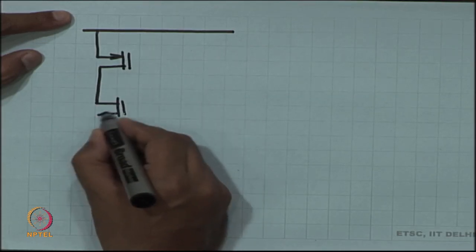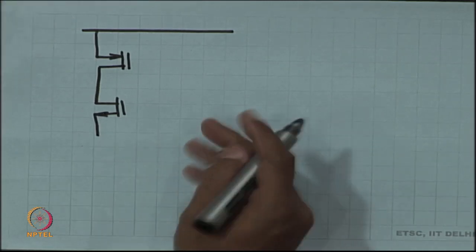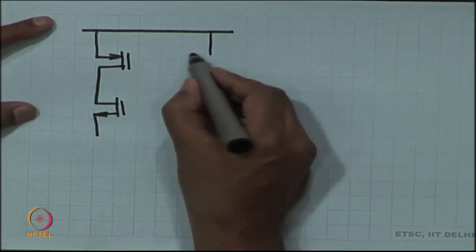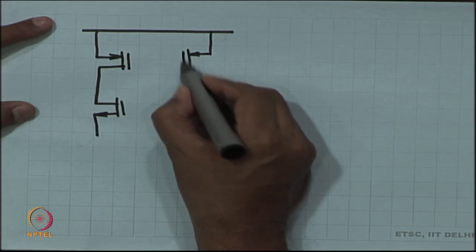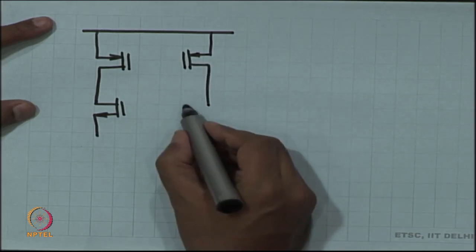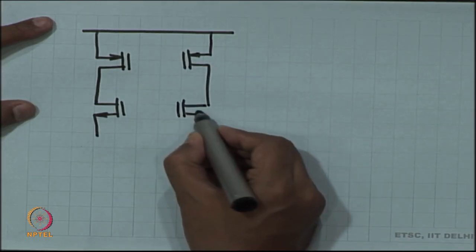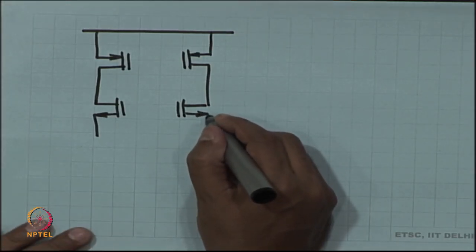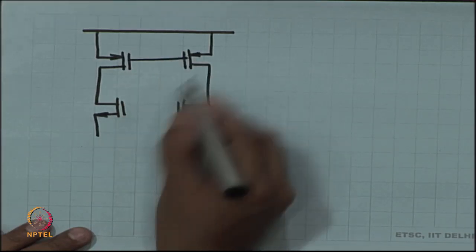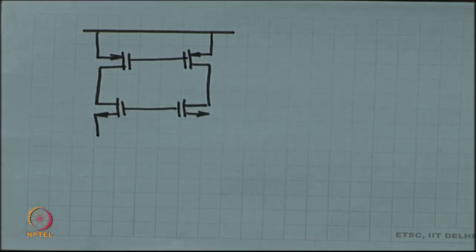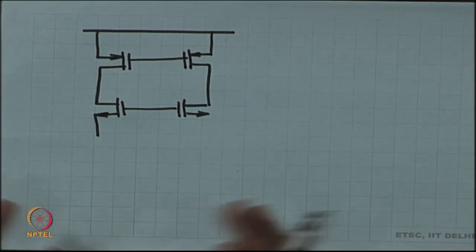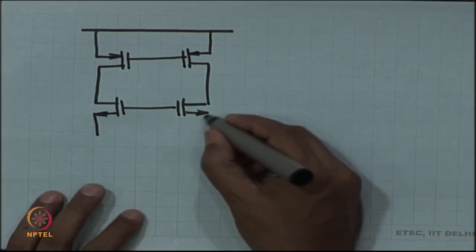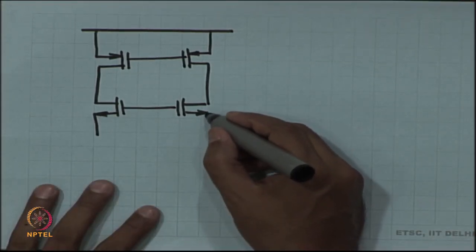And the way we were doing it, first we said let us just have one PMOS current mirror and an NMOS current mirror, but that did not quite work out because it could have conducted any amount of current. Next, we had a PMOS current mirror and we changed the ratio on that. The NMOS current mirror had a ratio of 1:1, in which case we found that no current goes through, and then we were working out a third one.